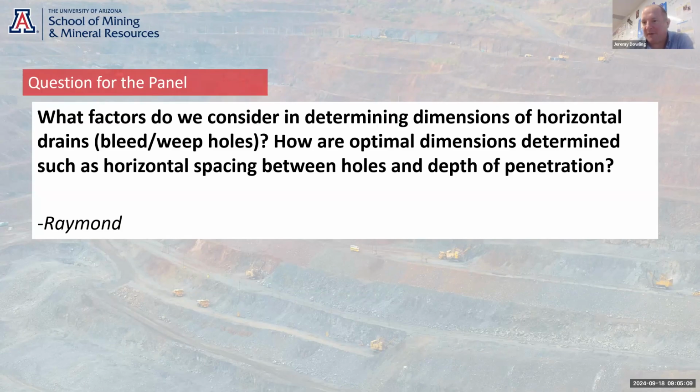And then the flow from those drains has just been allowed to cascade onto the bench where the drains were drilled. And that cascading water then ponds up and recharges back into the benches below. And it can also cause instability. So it's very important to reticulate the drain flow, put the water in a pipe or in a lined ditch or a lined something, and move it away from the bench and the area where the drains are drilled in order to prevent the water from recharging back into the benches below.